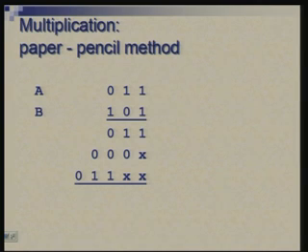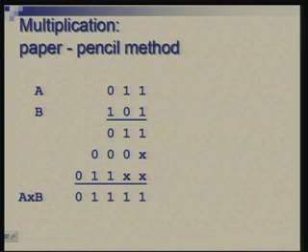And these partial products, each line represents a partial product, they have to be weighted appropriately, and the weightage here is power of 2, which means shifting it appropriately towards left, and simply add all these.